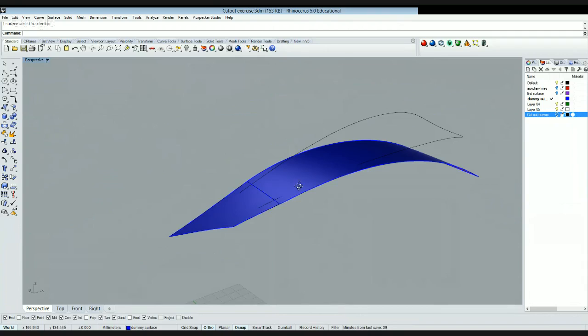Okay, so now you saw that I created this smooth continuation of my previous surface. And a nice useful tool that Rhino has to see how continuous or how tangent two surfaces are is the zebra command. So from Analyze Surface, you select the zebra. I select my objects, enter, and now you see this zebra pattern on the surface. You can create thinner lines, and you see that the connection is quite smooth between my two surfaces. Okay, so I close zebra.